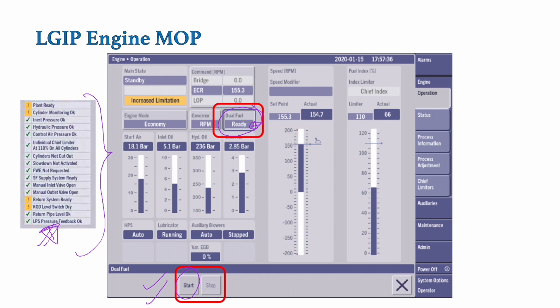And the last status that will come over here is stopping. When we are changing over from secondary fuel to primary fuel, at that time it will show stopping. All these statuses will be indicated on this button. And for stopping, as I have already told you, we have to press this button, then come over here and press this stop button. Pressing the stop button will initiate a few processes, basically purging out operation for the double wall pipes, and then only the engine will be stopped.